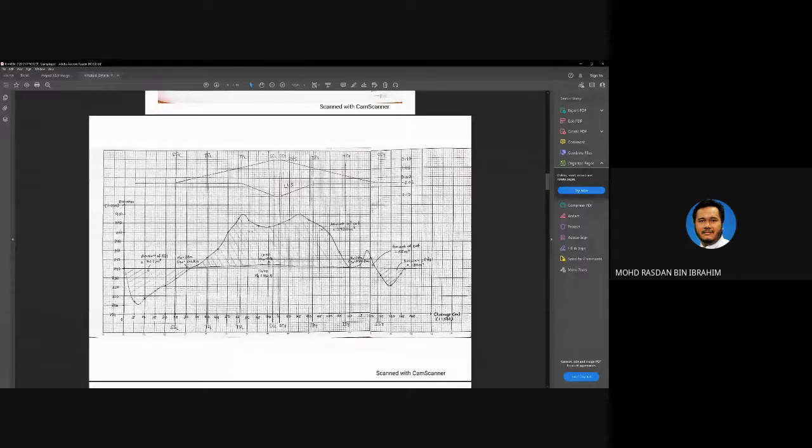She didn't write it here. Okay, so I assume this is maybe about the height difference, 842, 844, 2 meters different in 30 meters. About 6% maybe. So that is the maximum gradient.